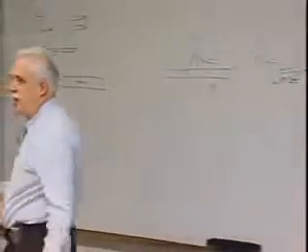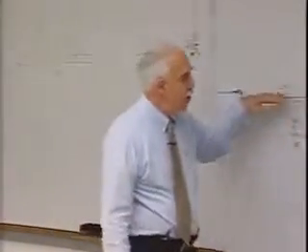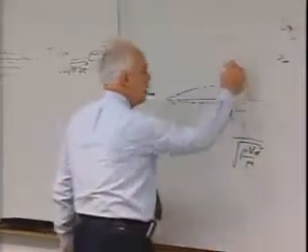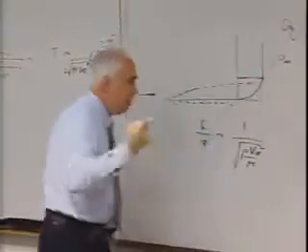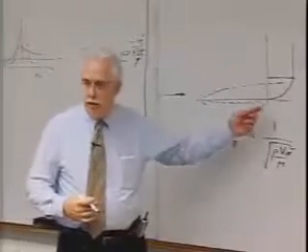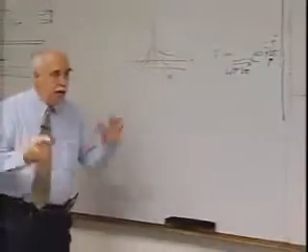Where does that come from? Same diffusion. It's a diffusion of the shear of this wall against the undisturbed flow. Whether it be the thermal diffusion associated with heat transfer, the diffusion associated with the shear, same phenomena.